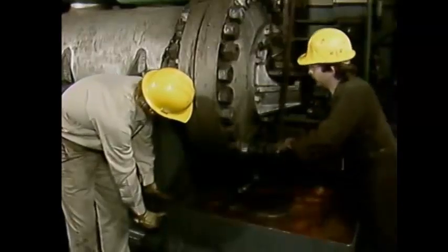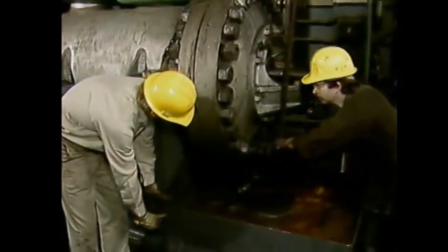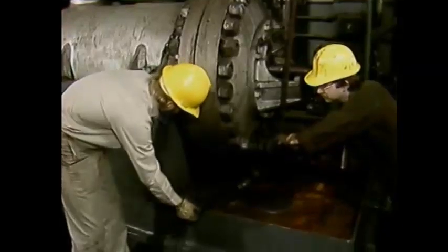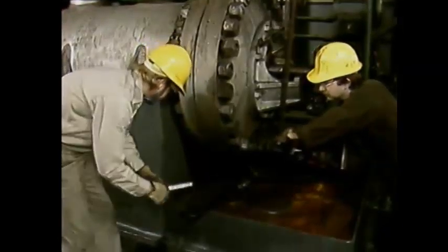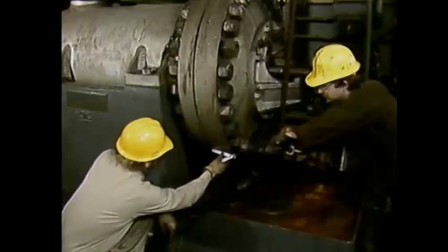Pneumatic tools and rubber hoses that are used with compressed air systems must be kept in good condition and inspected before each use. If the equipment is not in good condition, an accident could happen. If a 120 psi air hose parts, it could whip about and strike someone nearby, causing a serious injury.